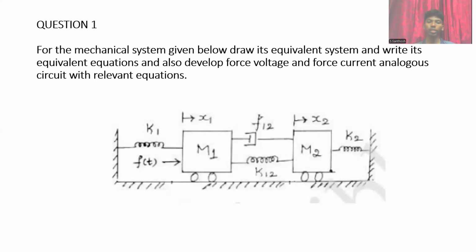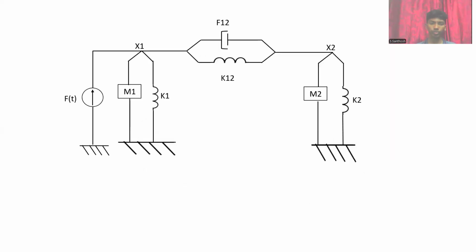For the mechanical system given below, draw its equivalent system and write its equivalent equations, and also develop force voltage and force current analogous circuits. So this is the mechanical system given for us. Now let's see how the equivalent system is drawn for it.